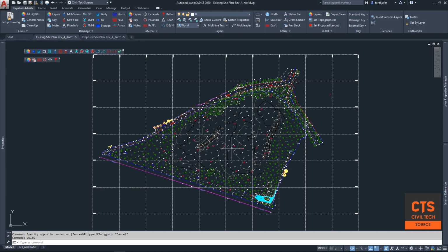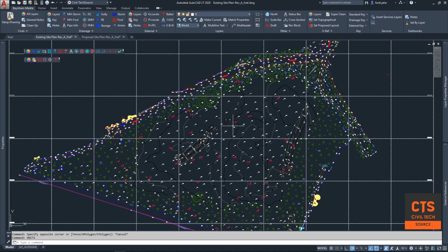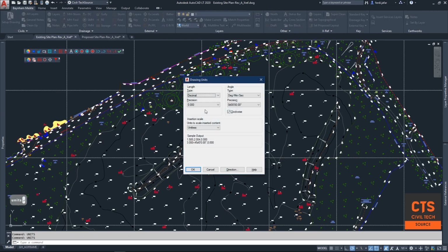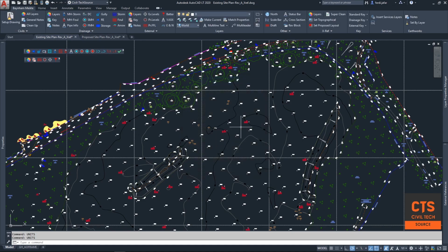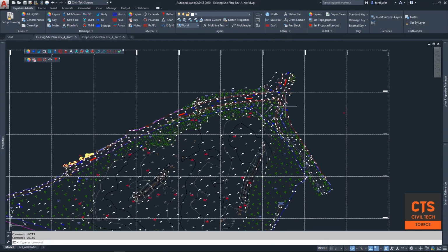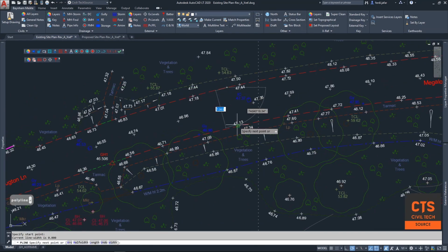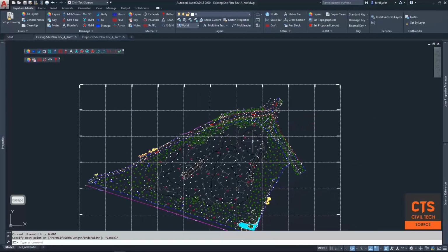Now, if your engineering drawing is set up to be meters, and let's say this drawing is drawn in meters but it's unitless, you can go ahead and change it to meters. But if your engineering drawing is unitless, you would want to keep it unitless as well, so that no conversion will happen. So since it's unitless, we hit OK, and we want to check in what units this was drawn. We've got a road here, so we measure the distance as 7.0. So basically we know that's in meters.